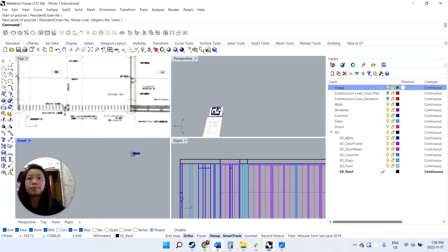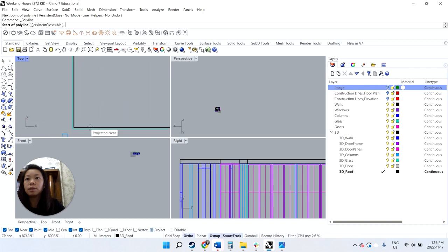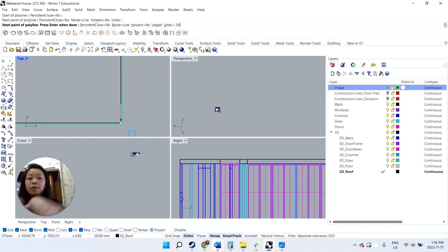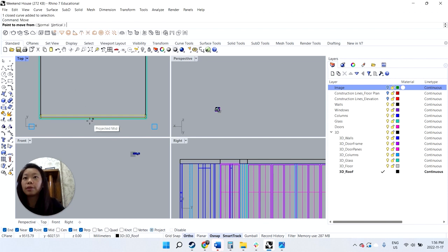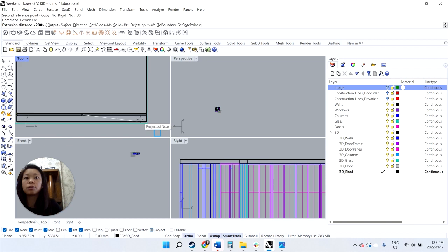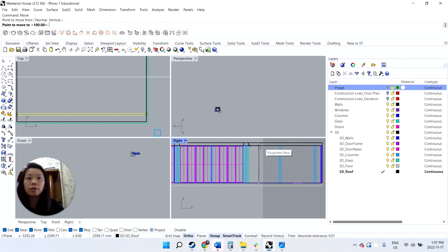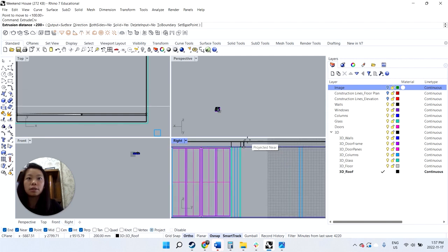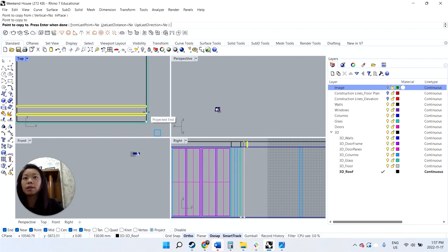If we go to the plan, zooming out, and let's say we just model one, right? So let's say 50. I don't think it was actually that thick, so maybe I'll scale 1D. Let's make it 30. I think it's more like 30. So that'll be a little thinner. And then I can extrude it. Actually, no. I'll have to move this. And now I can extrude it by 200. I can delete the curve now. So this is it.